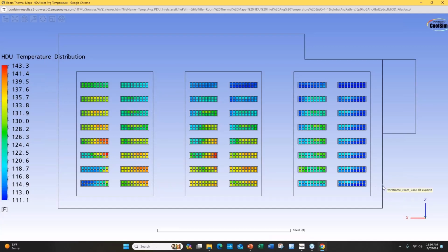Again, you look for the corners of your design, what we call the four corners. In this case, high temperature, worst wind condition is what you want to model to understand, in this case, what your aggregate cooling capacity will be on a given day. You can calculate it by understanding what that average temperature inlet is, and then determining what the efficiency of this heat exchanger is with an inlet temperature of 143 degrees. Or conversely, how hard your chiller's got to work to pump up or to boost or to lift the pressure in the compressor high enough so that the cooling medium is well above 143 degrees.